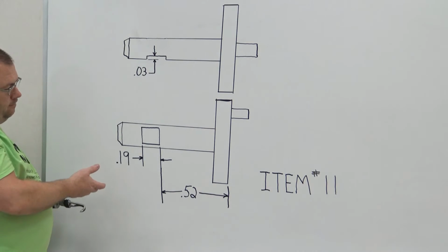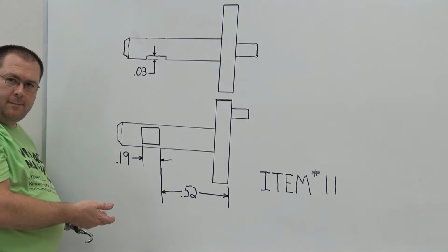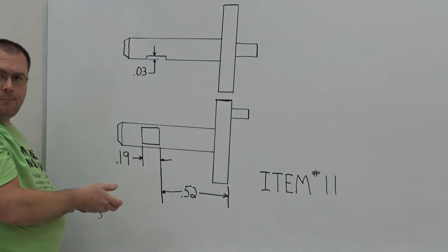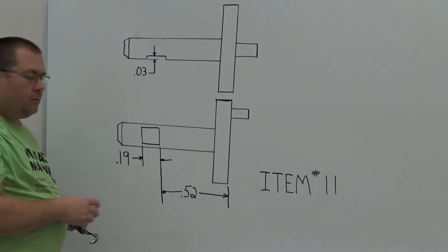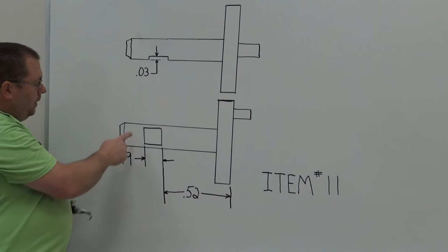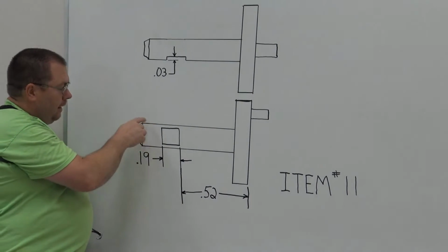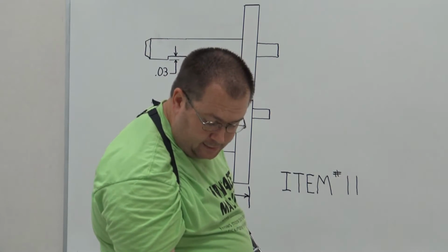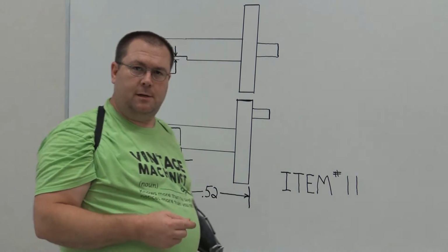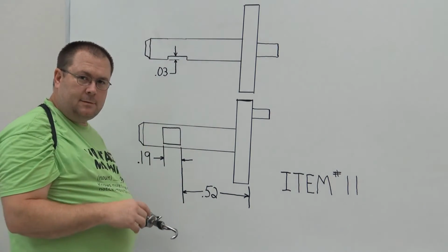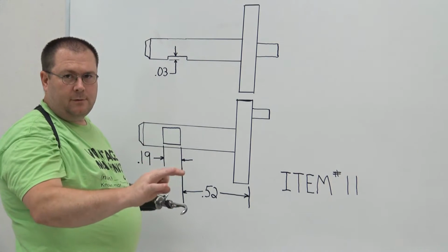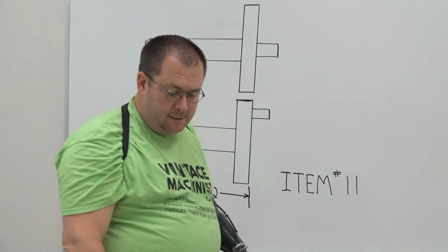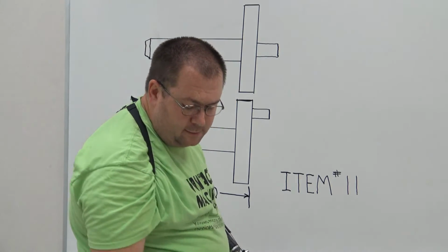Okay? Now, it might be difficult for you to start thinking about, but how are we going to hold on to a piece of round stock? Well, the round stock needs to be held in such a way that this is a precision surface. I didn't draw it up here, but your tolerance is a very tight tolerance on that 3/16 diameter, and it's a ground dimension, because when we buy miles and miles of that material, it's precision ground, and it's within a couple of tenths of a thousandth, okay? A couple of tenths of a thousandth, so way smaller than a thousandth of an inch.